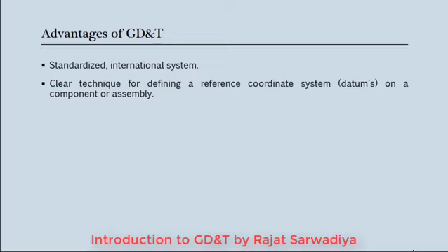As a designer working on a single part, I need to choose the datum in such a manner that it will be used for all operations on that part.